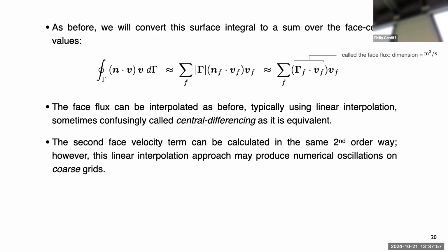But they've noticed from numerical experiments and some analysis that you can show that's not always stable. What I mean by stable is if you set up your solver to use this method, and you can force Fluent to use it, you might get oscillations in your solution. In the finite element method, we looked at zero energy modes. We talked about hourglassing, where you get oscillations in the displacement, a numerical error.